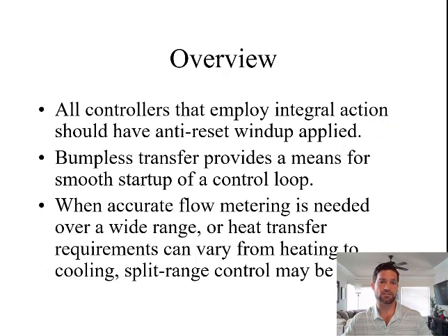Okay, so as an overview, we discussed a few things. All controllers that employ integral action should have anti-reset windup applied. Remember, not all controllers have to be PID. We could have proportional only controllers. Remember, that would be for an integrating process or a non-self-regulating process. Bumpless transfer provides a means for smooth startup and also for smooth transitions between desired operating set points. And then also for systems that require both heating and cooling or large flow ranges, we can use split flow control to achieve improved control in a given process.